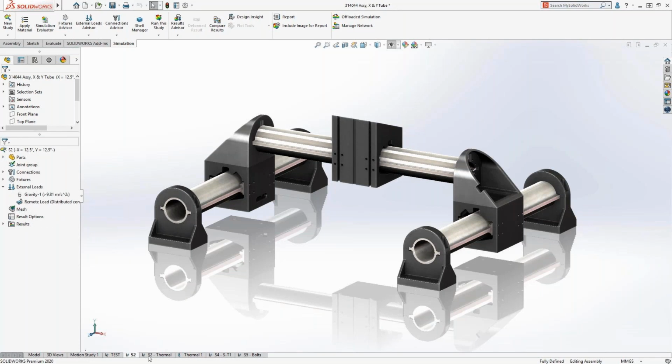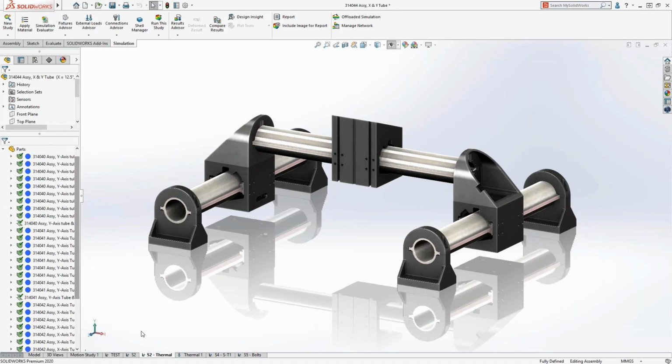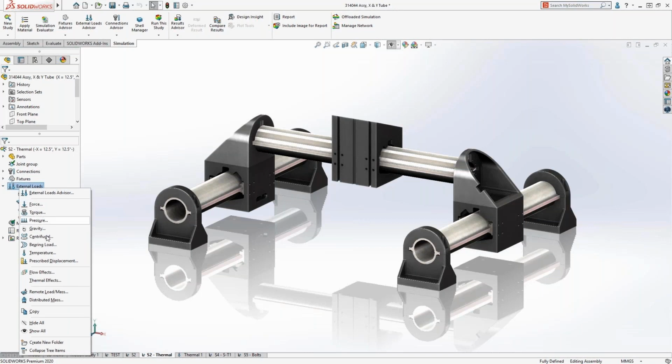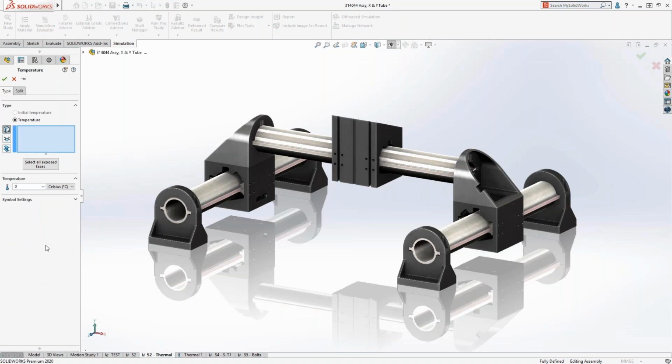Using the correct element type is also another really good way to maximize the performance in SOLIDWORKS simulation. So using beams when you have long, slender entities is a great way to do this. Previously, we were not able to do this if we had temperature constraints happening in our simulation. So, those would typically run a bit slower. We are now able to fully take advantage of this and apply temperature loads directly to beams or their joints. So this is the same process as any other load and any other entity now.